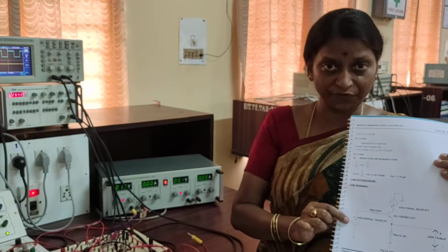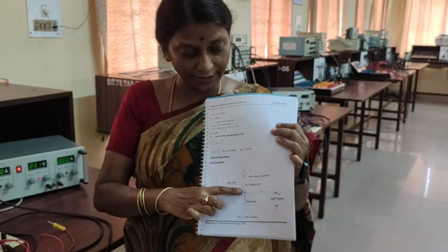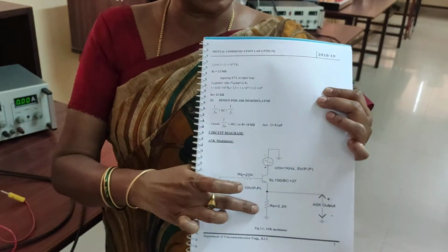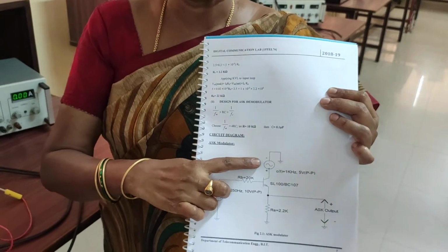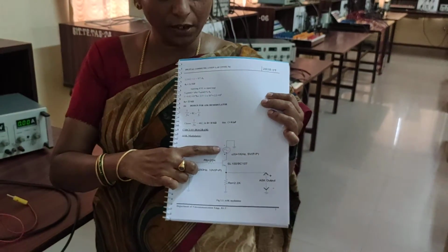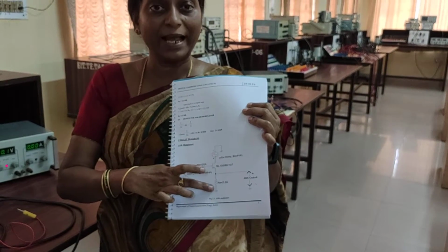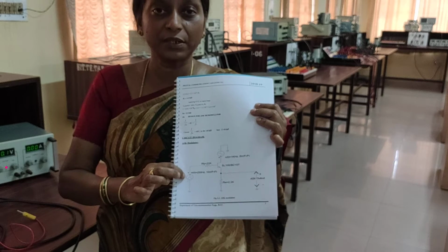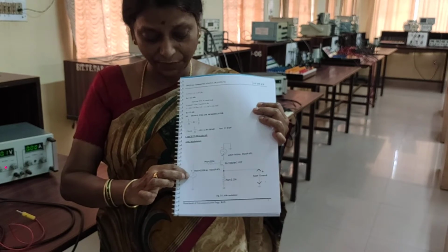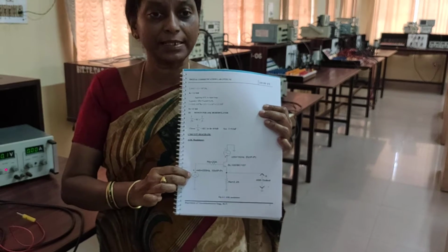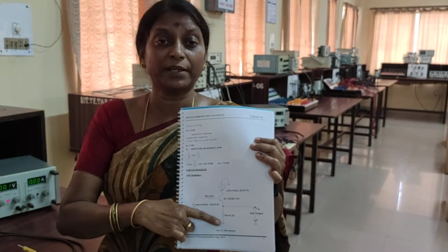Whenever the binary signal is +5 volts, the transistor will be in saturation, or in the on condition. When it is on, the collector current is approximately equal to the emitter current. So the signal connected in the collector, which is a carrier of 1 kilohertz, will appear in the emitter. It will appear as long as the binary is on. Since we have taken 250 hertz, as per the time scale, for a 2 millisecond duration the carrier will appear at the output.